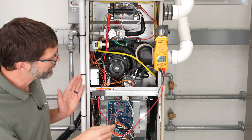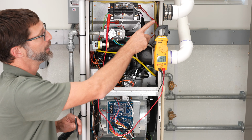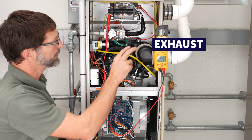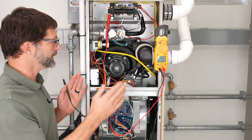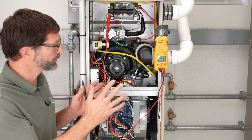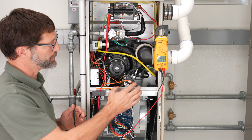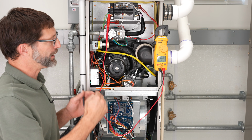There could be multiple different reasons why these pressure switches are not closing. There could be a combustion air problem where it's blocked. You know, it could be an exhaust problem where that's blocked. So there could be many different issues. The exhaust, maybe the secondary heat exchanger, that could be clogged. And so this is a safety switch, and you would never want to bypass that ever. You want to make sure to find what the problem is.